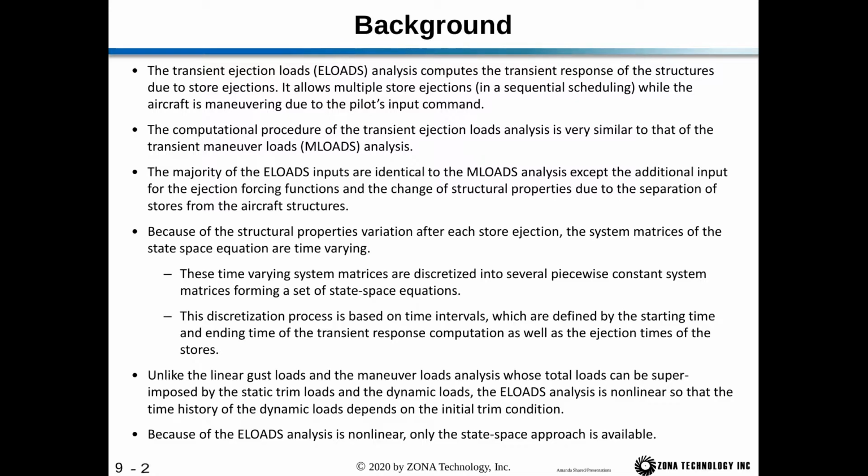Now, because of this, unlike the linear gust loads and maneuver loads analysis, whose total loads can be superimposed by the static trim loads and dynamic loads, the ejection loads analysis is nonlinear, so that the time history of the dynamic loads depends on the initial trim condition. And because the ejection loads analysis is nonlinear, only the state space approach is available.